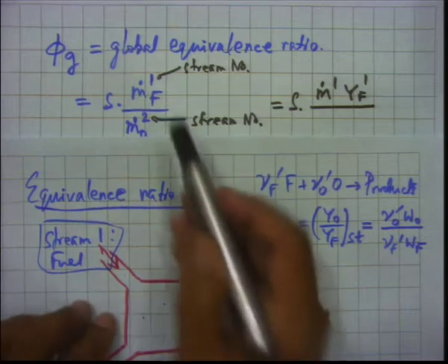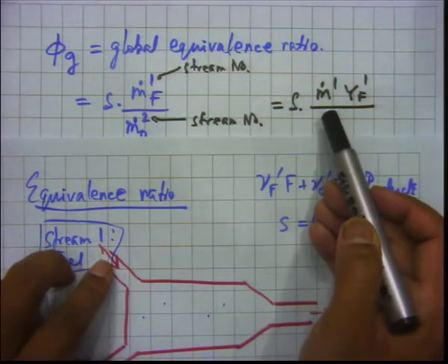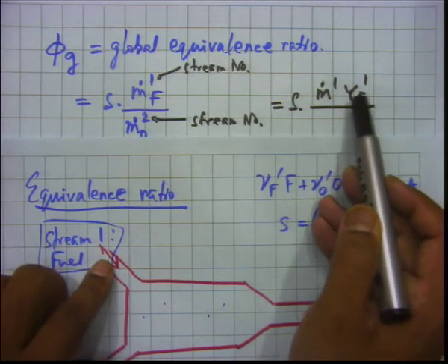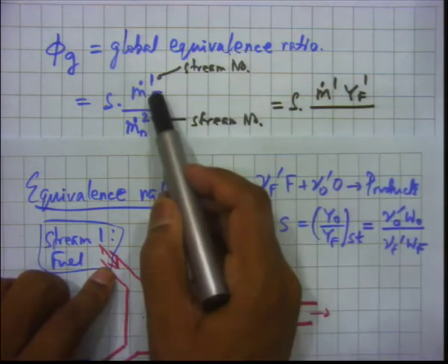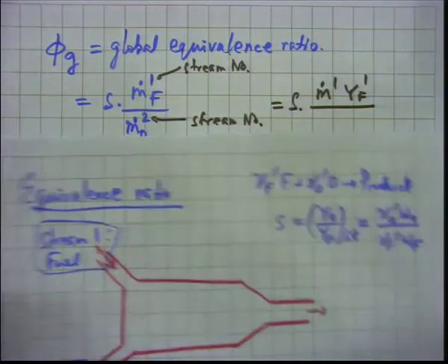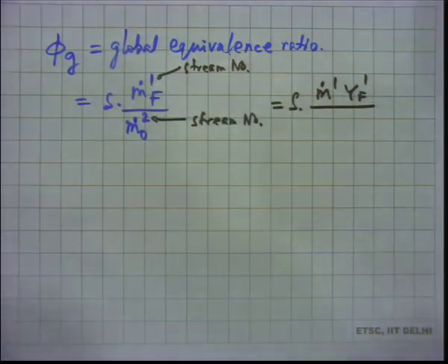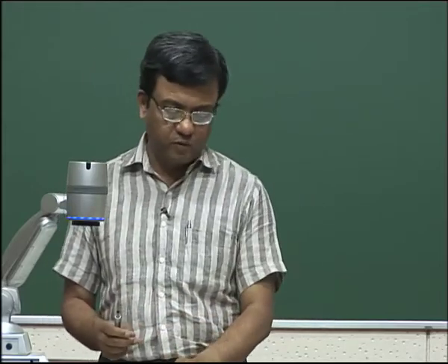All right. So the mass flow rate coming through this inlet multiplied by the mass fraction of fuel in that stream will give you the mass flow rate of the fuel coming through inlet 1, correct? Yeah. So in that stream, is there anything else other than the fuel? In general, yes. So YF1 is the mass fraction of the fuel.